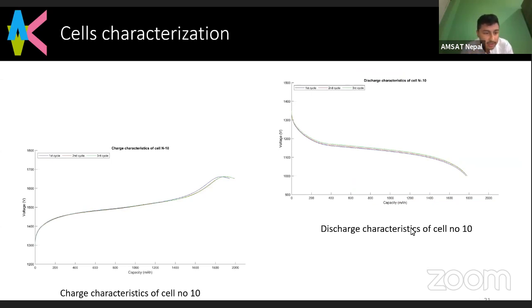So another question is, you use a nickel metal hydride battery. What differences are there in charging a nickel metal hydride battery and a lithium-ion battery? Because a lithium-ion battery is a little bit riskier compared to a nickel metal hydride battery, on the EPS board we should make sure to use more safety precautions for a lithium-ion battery.